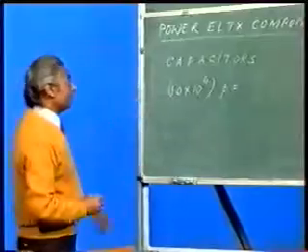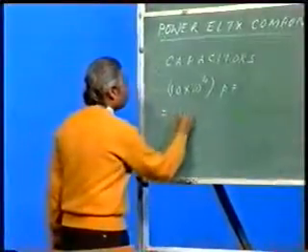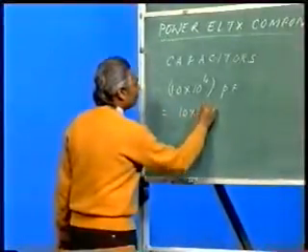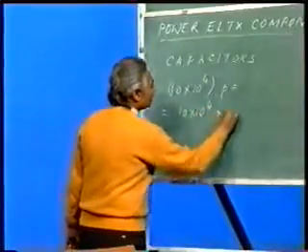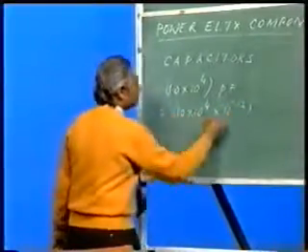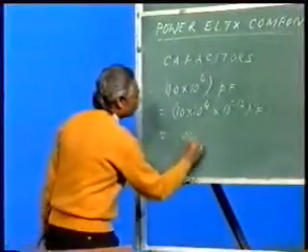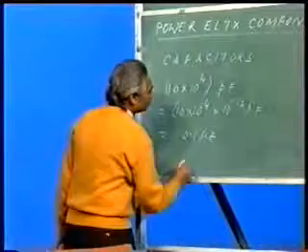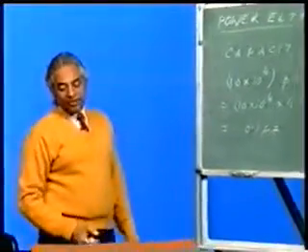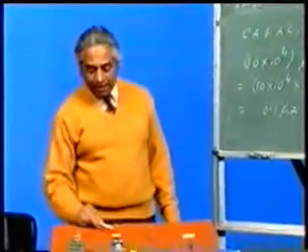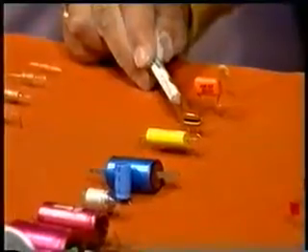Now if I change it, this will be equal to 10 into 10 to the power 4 into 10 to the power minus 12 farad, and on solving I get 0.1 microfarad. So the value of this particular capacitor is 0.1 microfarad.